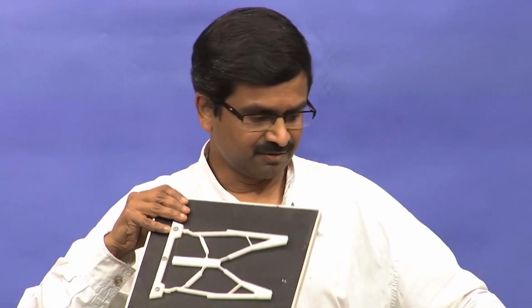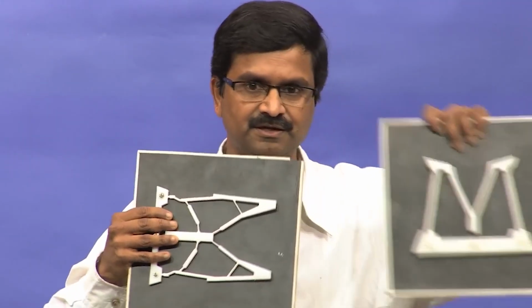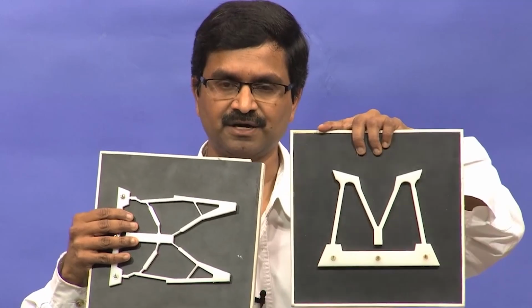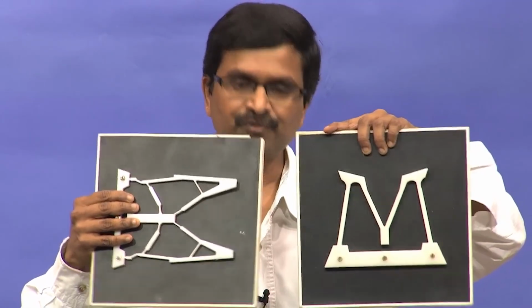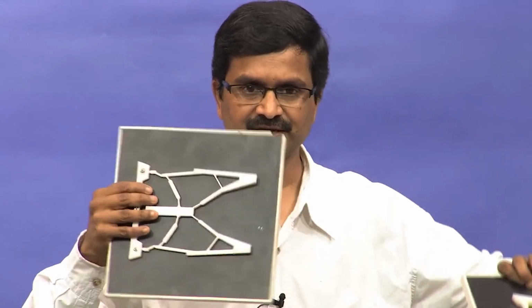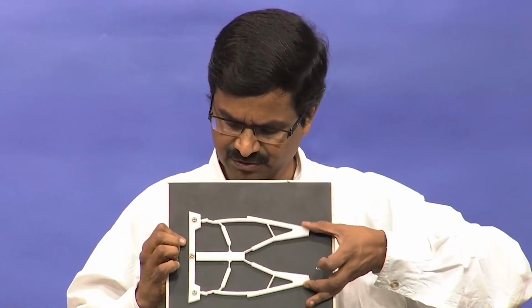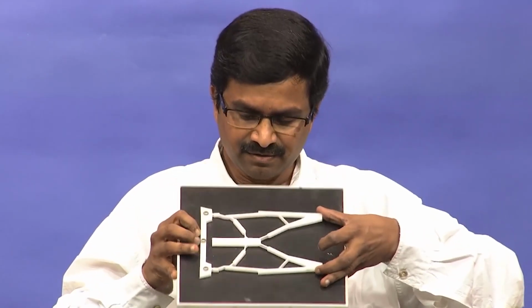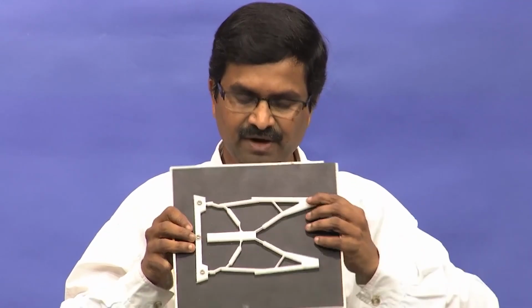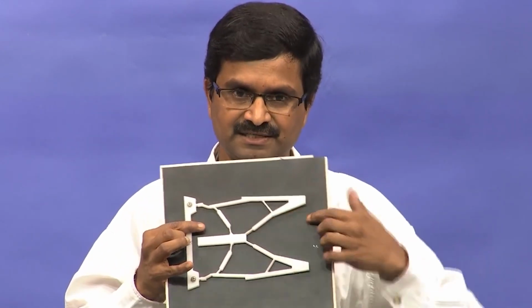Before I start, I have to say how do we compare the two, the one that has discrete compliance like this, and the other one that I showed which is this, which has distributed compliance. Which is better? If you were to play with these things, you will see the difference. Let me show it to you by first taking the discrete compliant one. If I apply force, it is going like this, but if I do not take enough care, I can flex these elastic pairs a lot.